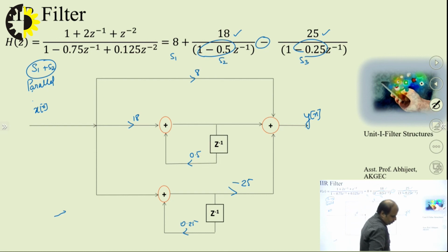In this lecture, we have developed that characterization of discrete time systems can be made using either the transfer function or difference equation or impulse response of the systems. Any of them are interconvertible. From the difference equation we can come to the transfer function, and vice versa. From the transfer function we can dwell upon the impulse response, and from the impulse response we can get the transfer function and the difference equation. IIR systems, infinite impulse response systems, are those in which the present output depends on past outputs and past and present inputs, which means there will be poles and zeros both.